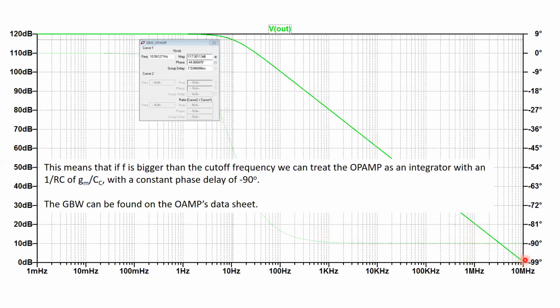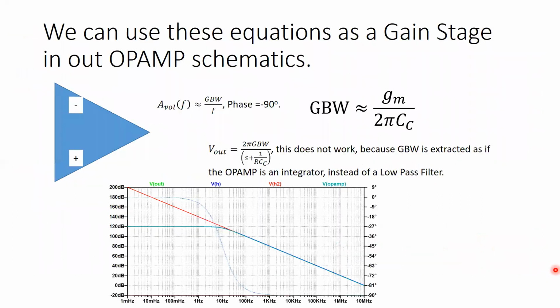10 megahertz. Now the other thing is they'll give you a value for open loop gain, which will be very close to DC. Now you can't draw a line from the open loop gain necessarily straight down in LTspice and expect your results to match, but it's a pretty good approximation for hand calculations.